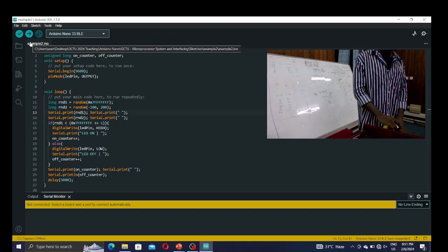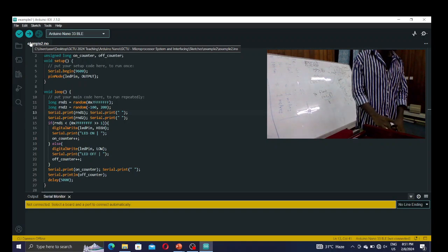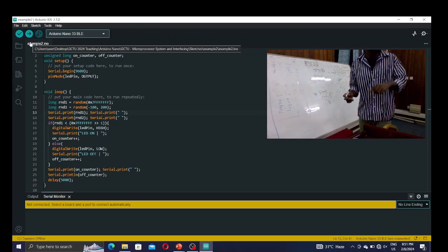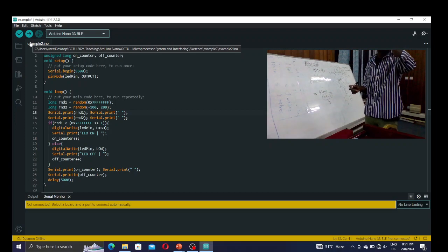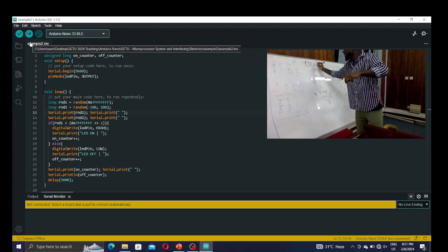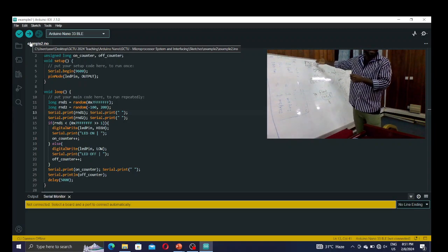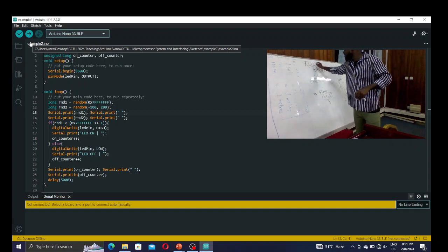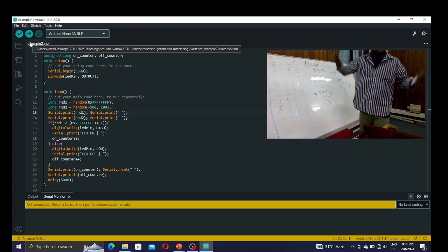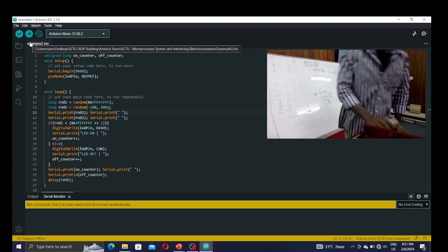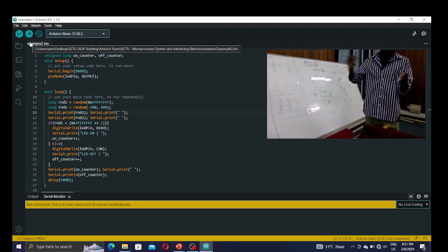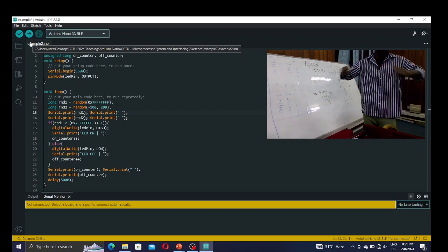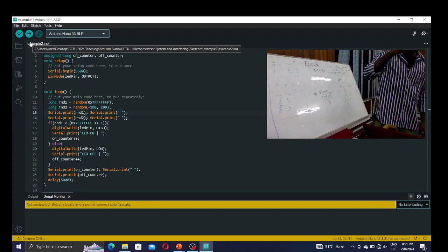Of course, the same way. In shift left, you remove the MSB. So if I say shift left by 1, I remove this one, push the rest, and put a 0 at the end. If I say by 2, I remove the first 2, shift the rest, and put two zeros at the end. Easy. Whenever I shift, a 0 is put in at the end or at the beginning, based on whether it's a left shift or a right shift. Understood?